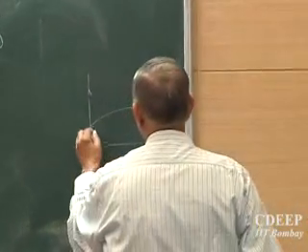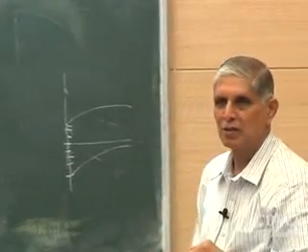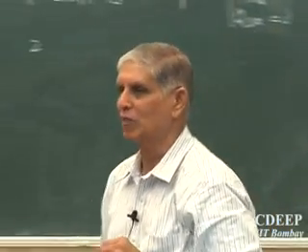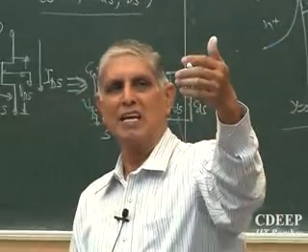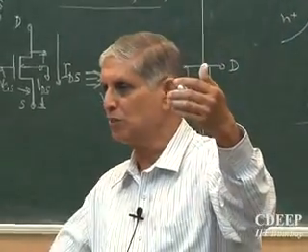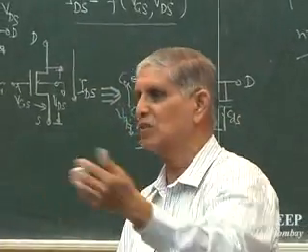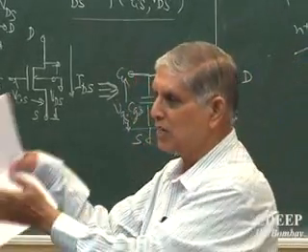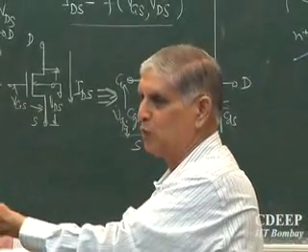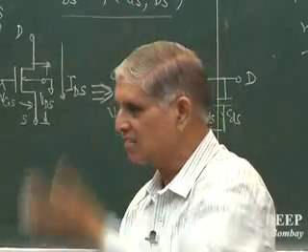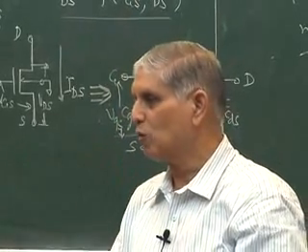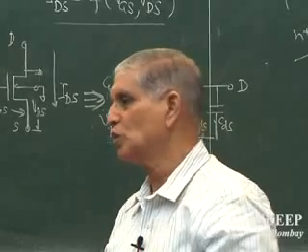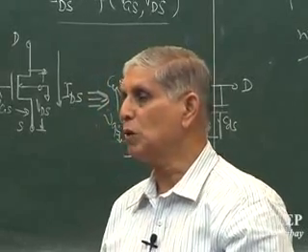Essentially, they give states in the band gap. The lower portion is called donor state, the upper portion is called acceptor state. This is also a partial assumption but valid enough in these cases. So the first time when I apply gate voltage, the charge is exchanged not with the semiconductor but with these states. They will fill up or empty depending on the charge I apply on the metal. So the semiconductor is getting screened, that is, it doesn't get the voltage I am applying, but first the states fill up. If the threshold has to be attained, you may require additional voltage; first they will fill up and then semiconductor bending may start to get you to threshold. So there is an additional problem, and this will keep on changing as the charge changes.